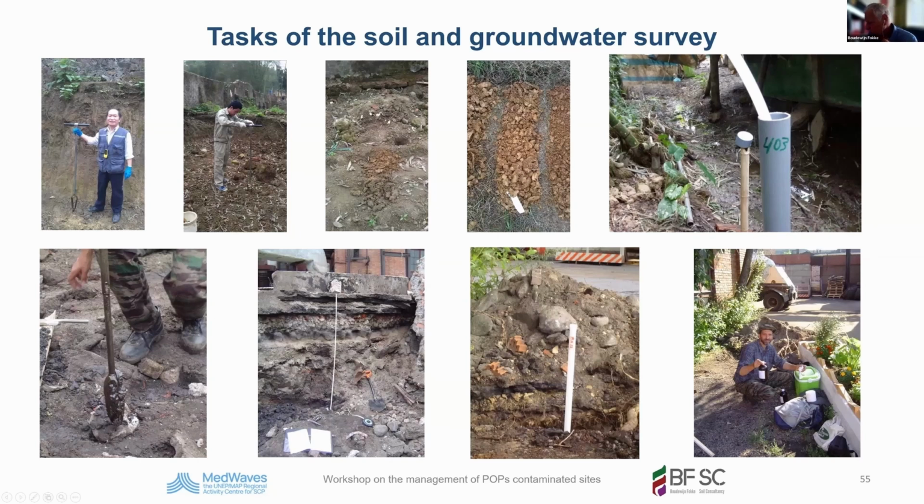My bore logs. Here a detail of the profile, and here sampling groundwater, my cooling box to take the samples under a cold chain to the laboratory, my labels, and now after taking it goes immediately into this box with ice packs and brought to the lab.